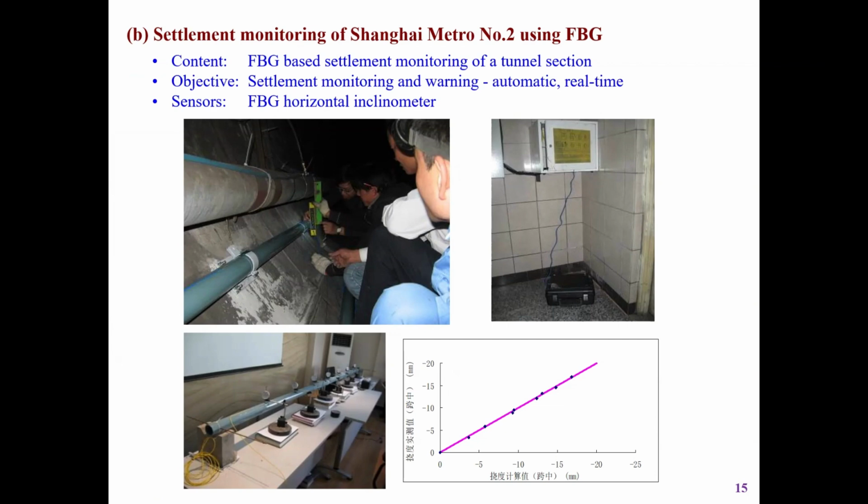So we put a tube here, like a PVC pipe. We put a sensor on the top, measuring strain on the top and strain on the bottom. If the tunnel goes up or down, the pipe will bend, similar to a beam. So we measure strains, and from the strains we can convert to the deflection.